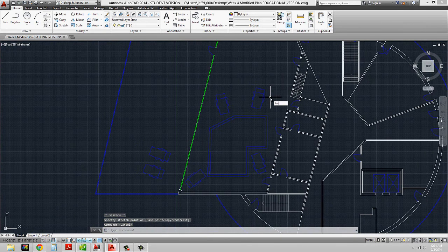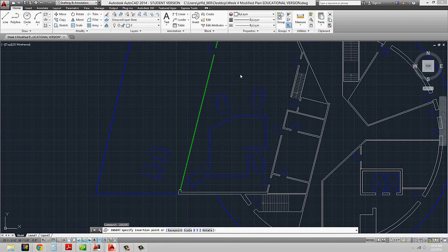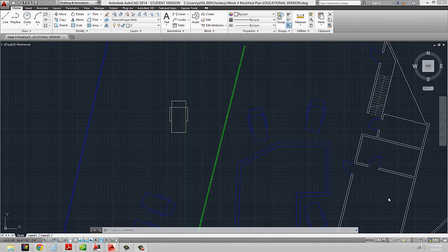And then if I insert it again, you'll see that it will always insert it as I had originally drawn it. The key advantage of using blocks lies not only in the fact that they allow you to copy and move a large number of otherwise separate objects as one entity, the blocks give you the opportunity to be edited. Upon editing a block within the drawing, all instances of the block are updated automatically. So basically this happens in what's called the block editor.